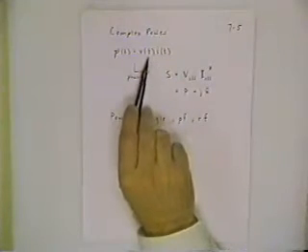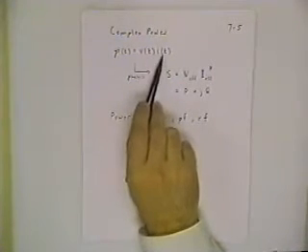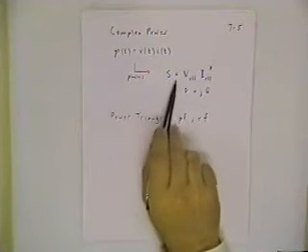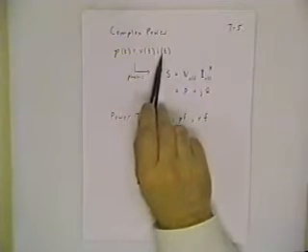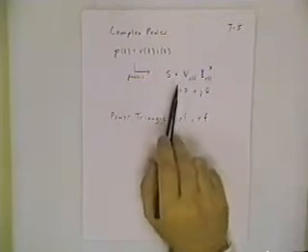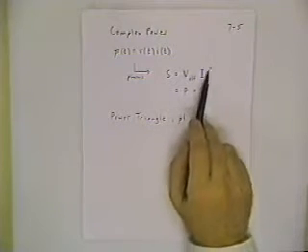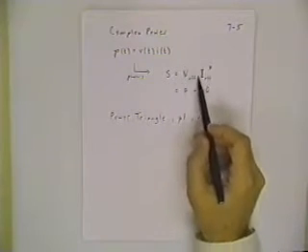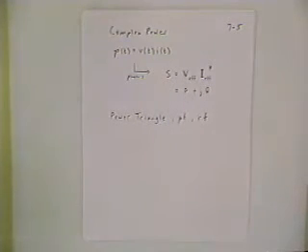Okay, let's talk for a minute about complex power. How power appears in AC circuits is the same way theoretically as for DC elements. You have a power that's equal to a voltage times a current. And if these are AC voltage and current, then they each have their phasor equivalents. Now the phasor equivalent of this equation is not just V phasor times I phasor, but for a very similar argument to what I just made, you multiply by the conjugate of the current. This is where the concept of effective value or RMS value comes into play in power calculations.